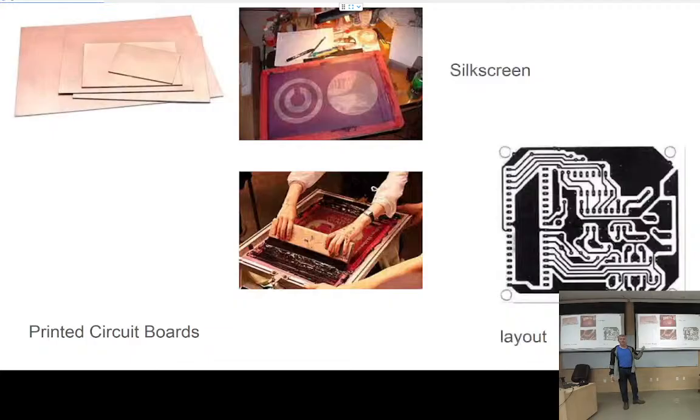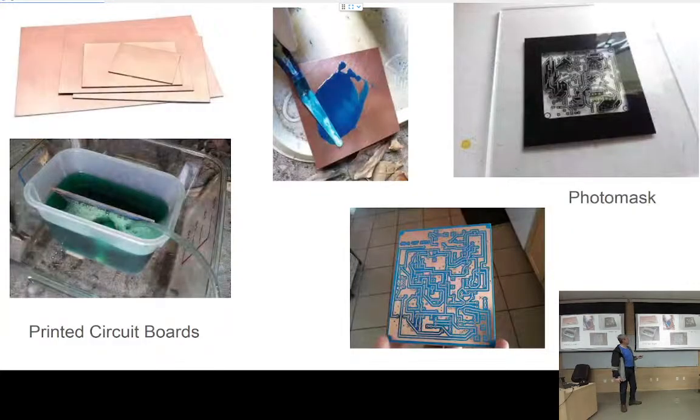And let me show you the evolution of that, because we had a technology since the 19th century. One thing that was developed in the 19th century was photography. And so why not use photography? You can create a transparent thing with the drawing that you want, like a negative with a film. Then you cover the copper with what we call a photoresist. It's a material that changes its property when exposed to light. Obviously, you shouldn't do that in light, otherwise it'll be ruined.